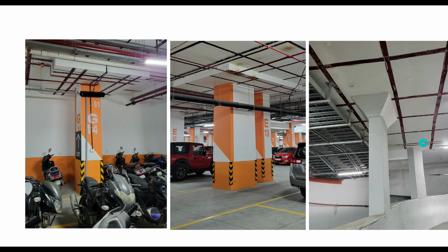Why have they done that? Because punching is not that much over there. So based on the kind of punching shear you are getting, you can either go for a drop, you can go for a column capital, or you can just go for a flat plate system over there. All of them can be combined in one single system altogether. It is not like if you have drops, you have to have drops throughout the entire project. That is not the case.